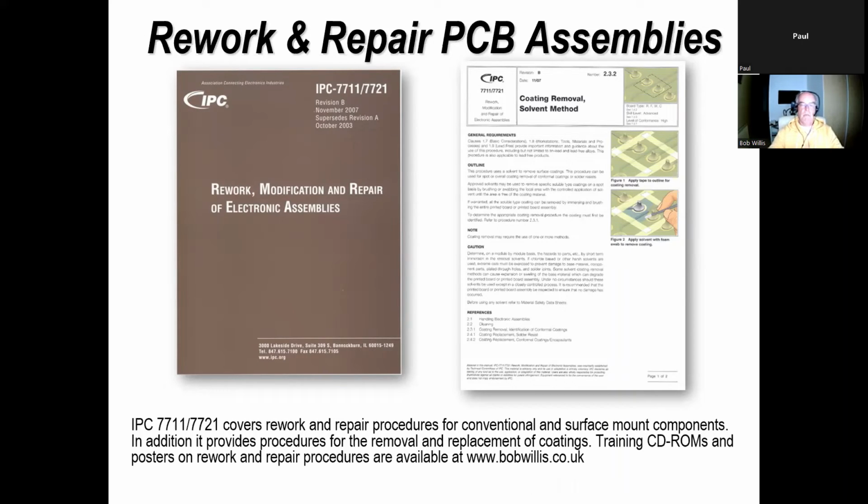I personally believe that it doesn't matter what type of conformal coating you're using, you should remove it to solder through. You shouldn't solder through. Now, people can, they do. But what tends to happen is all of the coating gets all over your soldering iron. If you're using a proper vacuum desoldering tool for through-hole components, which you should do today for lead-free technology, not one of these horrible $5 solder suckers you get given away free, you are sucking the conformal coating into the tool. And if your maintenance department or your operators don't clean the tools regularly, then it's not going to work very well. So just removing that small area to remove that part, because you're going to have to replace the conformal coating anyway. Personally, I think that's the right way of doing it.